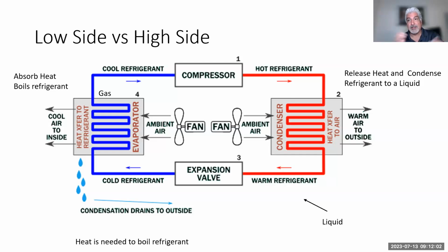So that's the new stuff that makes it easy. The question is, do I have access to it? Because if I work on a Ram Dodge, you can't get to anything there. You have to pull the whole thing just to see the evaporator. So I understand that. But we can also use our temperature probes to look at the inlet and outlet of that evaporator and see if we do have a change in temperature.